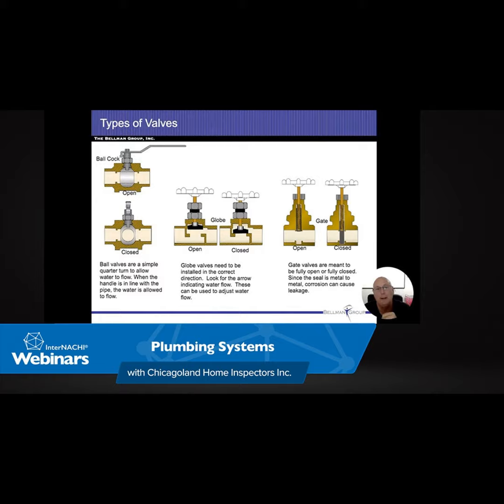Now these gate or globe valves that you see there, anything that you have to twist like that, I would never touch that thing. In fact, I try to avoid turning any valve. Typically they're one-timers. I would explain this to my client as well. If there's an emergency and you have to turn the water off, this is one of the locations where you could do that. Number 7 is also a shutoff valve, but that's a ball valve, and we'll talk about that in a minute. These gate and globes, they're notorious for leaking, especially if they've never been used for years. When I turn it off and open it up, they're just notorious for leaking. I don't know any other word to say it.